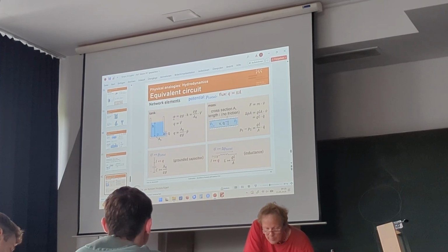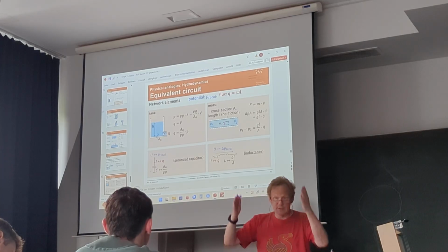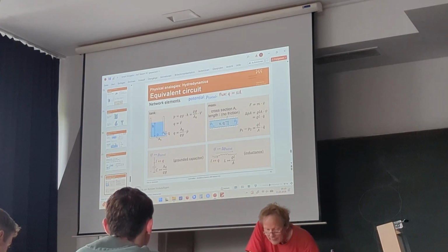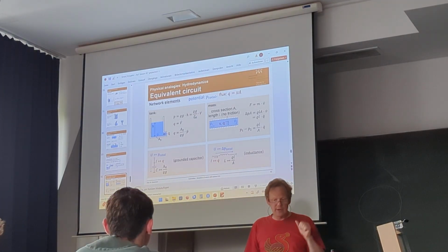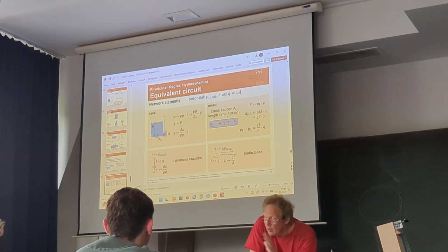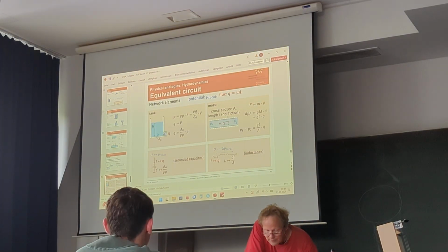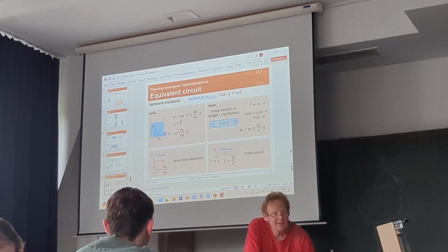And now we have our formulas. We know the static pressure, at least. The pressure is rho times g times height. We have the height, in this case, if it's a straight tank. We can write the height as a volume divided by the cross-section area. Really only if it's a straight tank, that's clear. And that means the pressure here has to do with the volume. If you change the volume over time, we have a V dot, that is the volume flux Q.